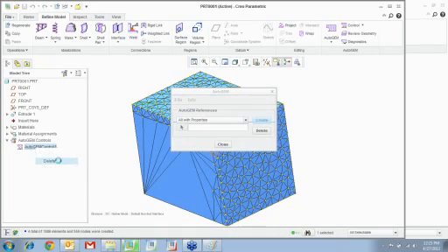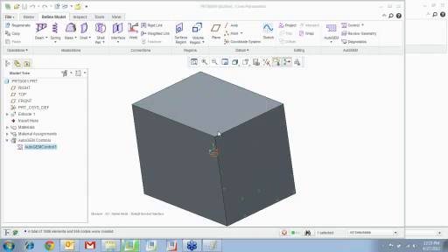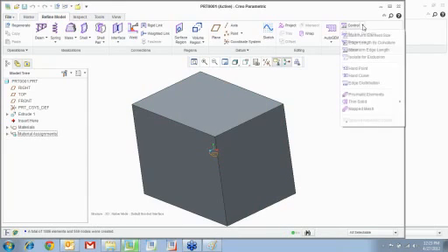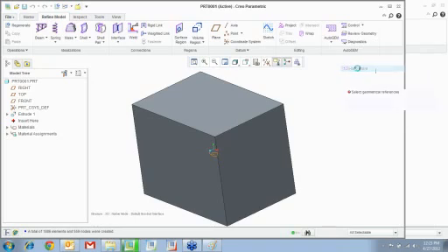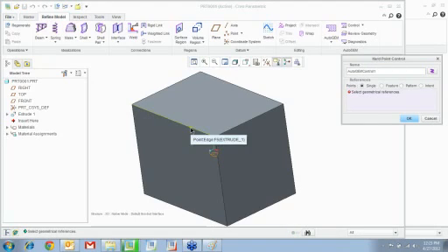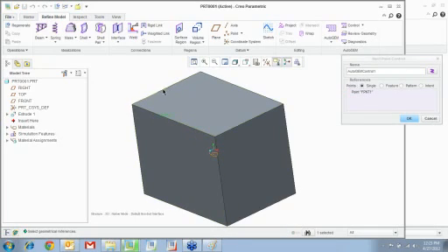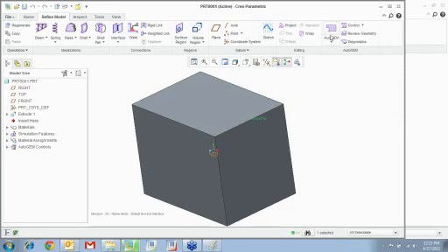I'm going to go ahead and delete that mesh control. Next, edge length by curvature. You have minimum edge length. You can isolate certain elements for exclusion. You can create a hard point or a hard curve. You can say, hey, you know what? I want to pick a point over there, pick a point over there. So I'm doing that.